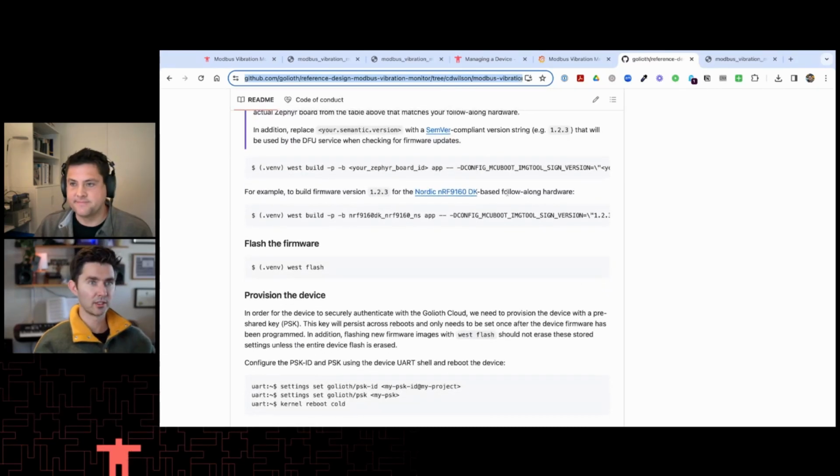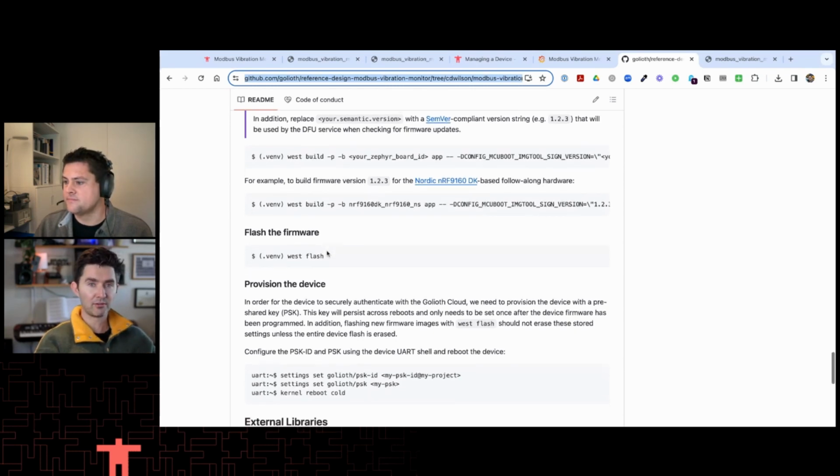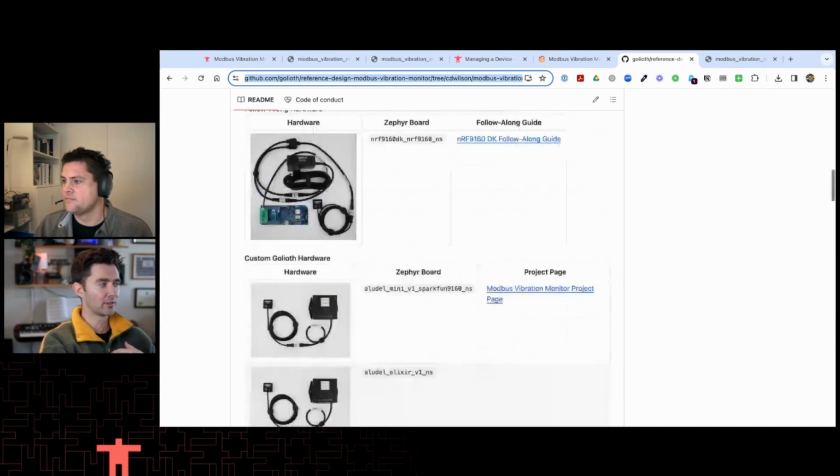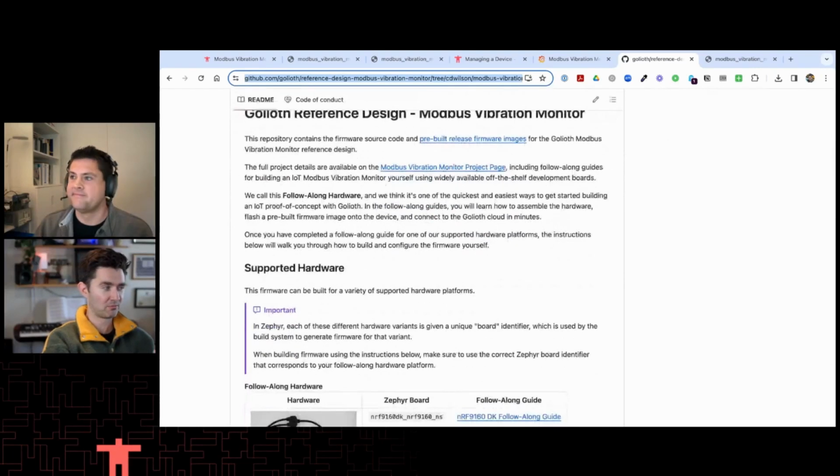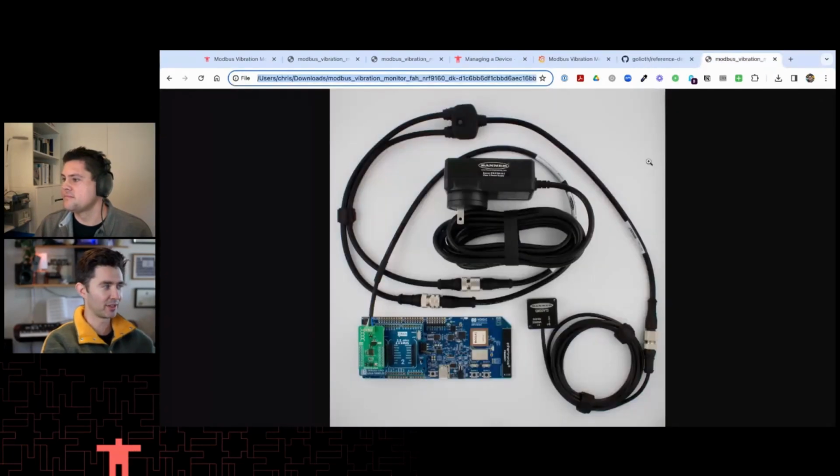So say someone wanted to take this, start building a product off it. That's great. Probably don't want just what Chris has done here, even though it's amazing work and it does everything on this sensor. You might want to add other stuff in, right? You might have another click header or whatever. Yep. Or because it's Modbus, you actually might move to a different sensor, right? That is actually probably one of the most powerful things about this specific reference design, is that it can be redeployed to another sensor by just pulling that sensor's information off of it instead, right?